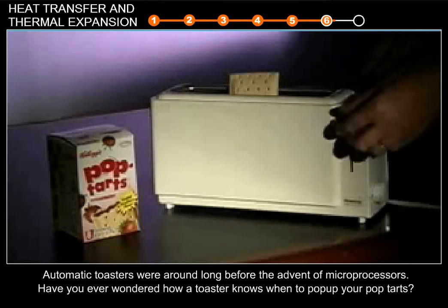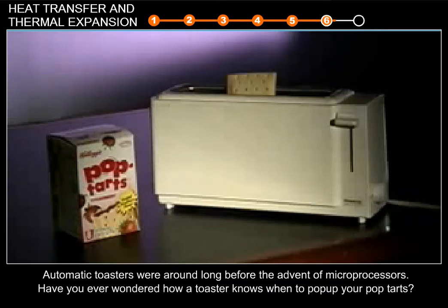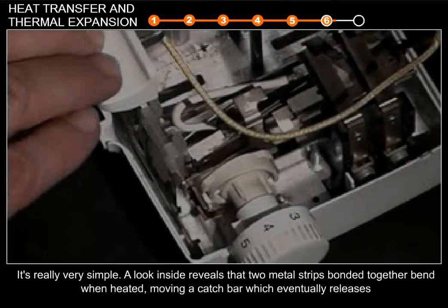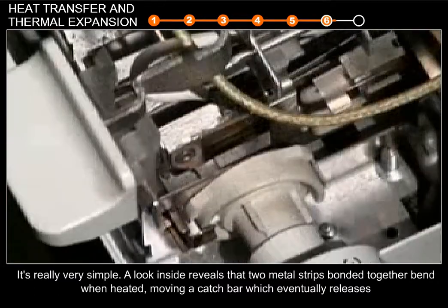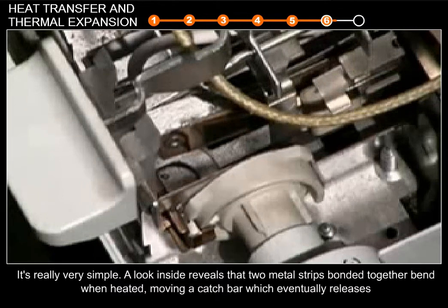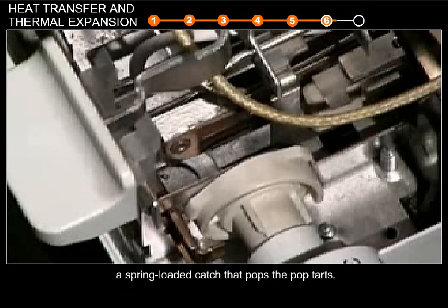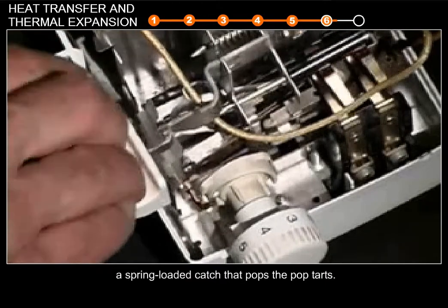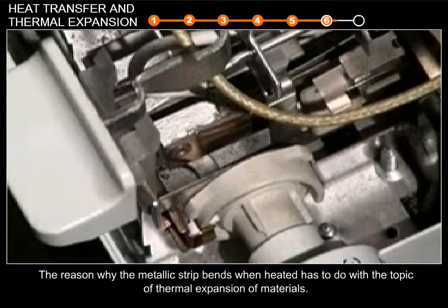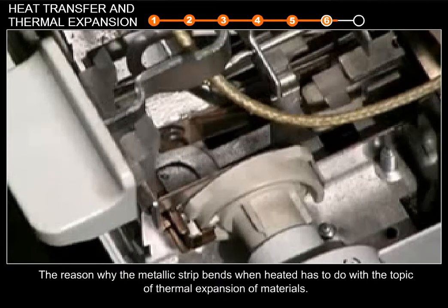Automatic toasters were around long before the advent of microprocessors. Have you ever wondered how a toaster knows when to pop up your Pop-Tarts? It's really very simple. A look inside reveals that two metal strips bonded together bend when heated, moving a catch bar, which eventually releases a spring-loaded catch that pops up the Pop-Tarts. The reason why the metallic strip bends when heated has to do with the topic of thermal expansion of materials.